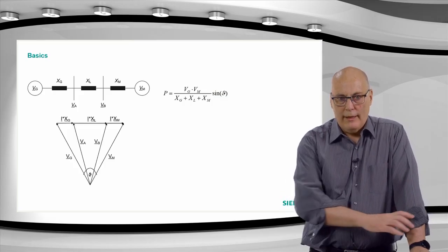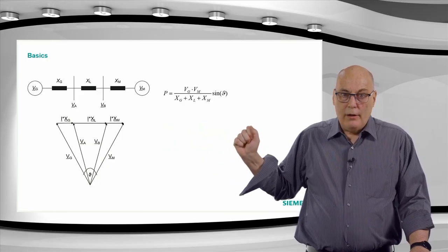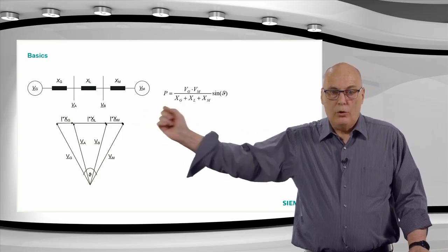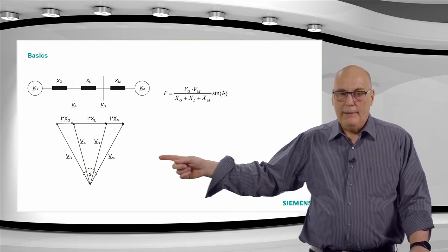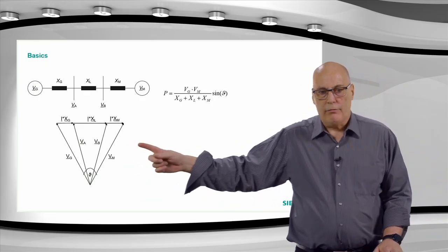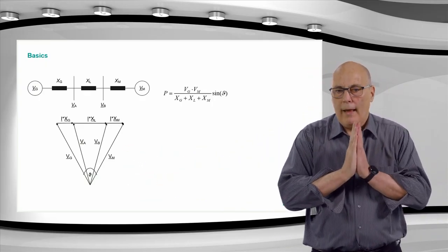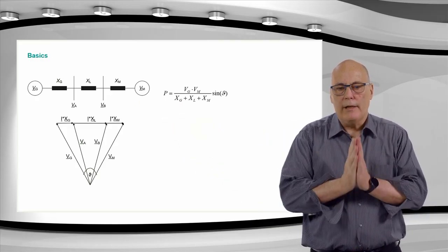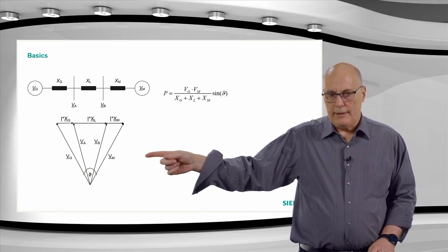That's shown in this diagram over here. What is missing in the diagram is obviously the load current, but that is shown at the top here. You can see the load drops, the three load drops. The load current would effectively be exactly at the bisection angle, vertical at the bottom from the source upwards. That's the load current. Remember, for active power, for P, we get real power only if the current is in phase with the voltage. So in this case, it would be exactly in the middle.